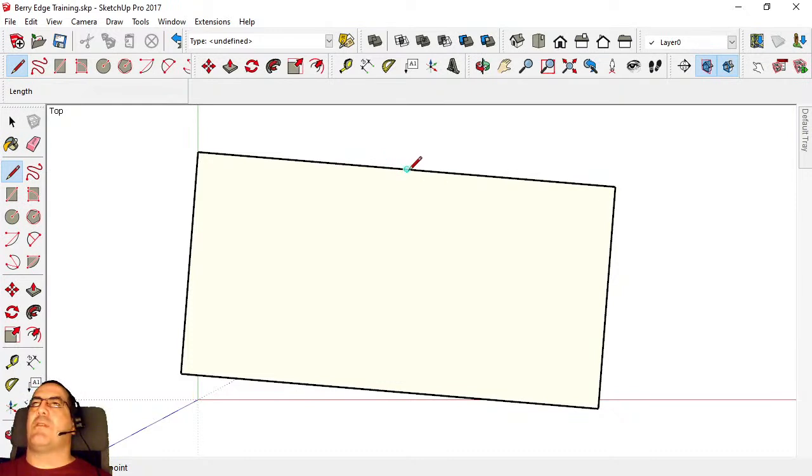And if you have your snapping tools on, the snapping tools in SketchUp work exactly the same way as the snapping tools in things like QGIS. You will see that that'll actually jump. So as I move closer to it, there you go. Even though the pencil's not exactly on the midpoint, it's snapped to the midpoint because it's saying, look, you've been very close and very slow and deliberate. This is probably what you want. If we click once and then move down across the shape, you'll see that we'll get a green line.